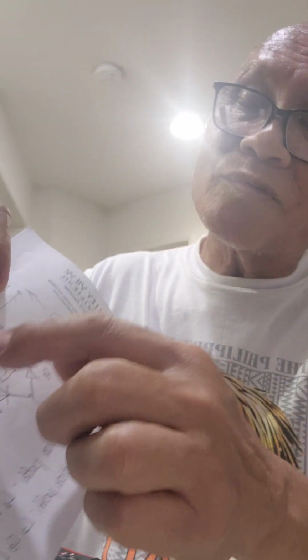And to check the last remaining diode, it will be D2, right? So we maintain the positive terminal of the tester connected on the positive terminal of the network, and the negative terminal will be on line number 2. Okay, so we are done now with line number 1, because for line number 1 we are checking D4.